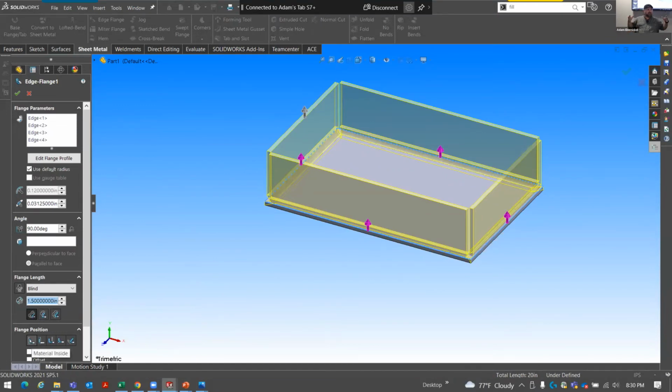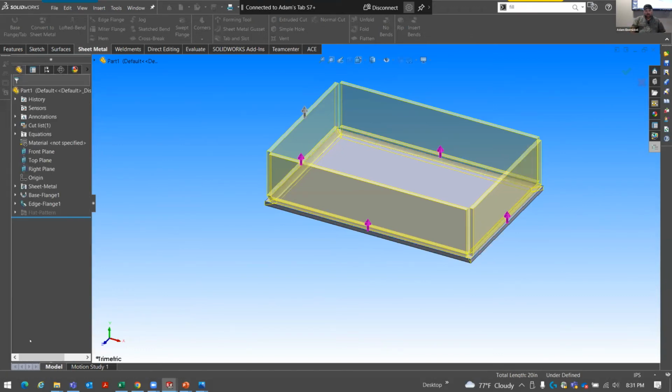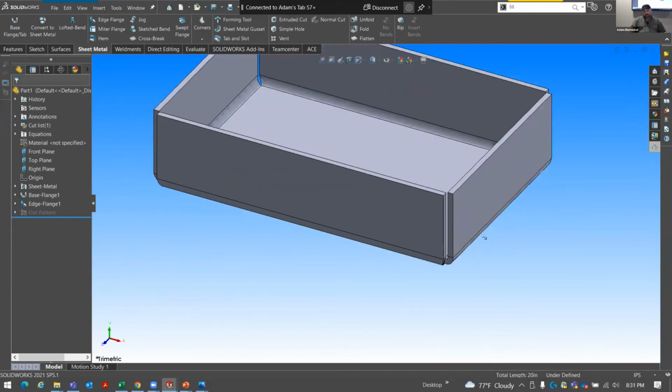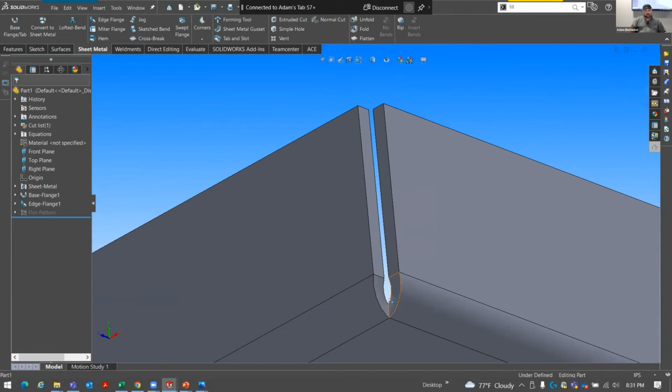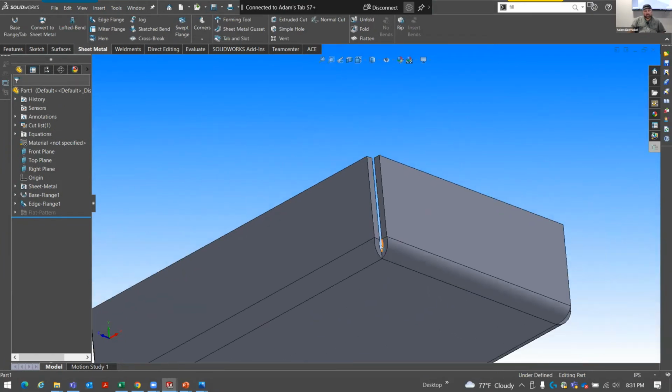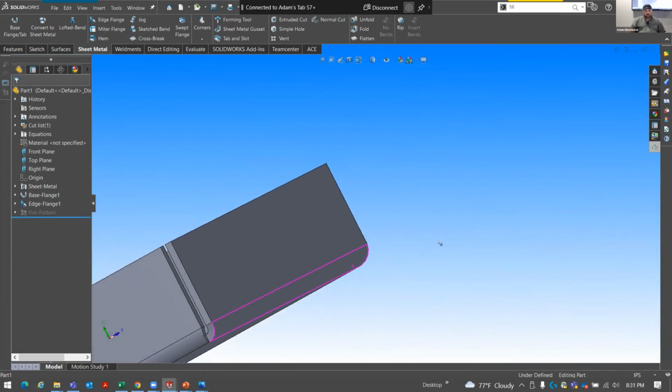So whatever I made the parameters of the width and length of that plate, I can keep it within that, and look what it does for me. It doesn't tear it inside of the other radius, right? It still can do a tear, and we can adjust this gap distance based on our tooling too, right? We can adjust that gap distance, but we have it all kind of equally torn. The press brake is going to be much happier bending something like this versus the other one that we showed where it was torn all the way inside the radius.